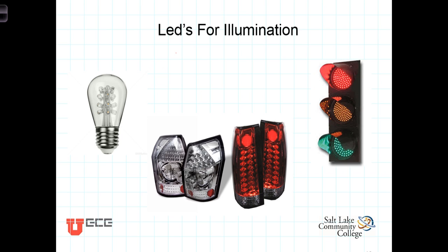Let's say it differently. A 60 watt incandescent light bulb gives off a certain amount of light, but it also has an awful lot of heat associated with it. That heat is an inefficiency of an incandescent light. Replace that with an LED, and it will use about 6 to 10 watts, so approximately 1/10 as much power. The LED is much more efficient and doesn't get nearly as hot. And if they're manufactured correctly, the LED light bulb should outlast the incandescent or the compact fluorescent light bulbs also.